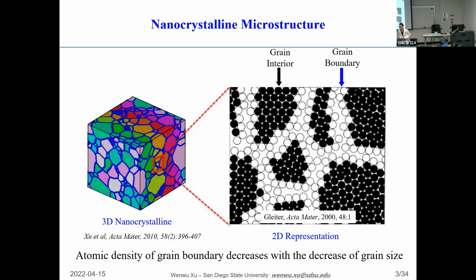Just for comparison, what is the typical grain size of manufactured metal? In this case, it will be under 100 nanometers, from a few nanometers to... I meant to compare nanocrystalline materials to conventional materials. Microcrystalline material. Yeah, but how much larger are the regular ones? Regular ones are from a few micrometers to a few hundred micrometers. This would be a regular grain size for the metals we are using.